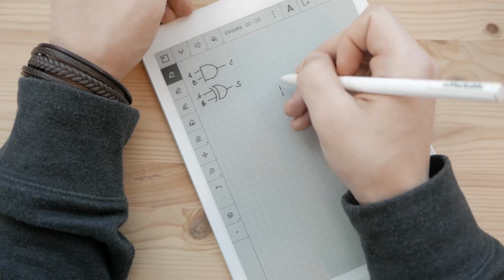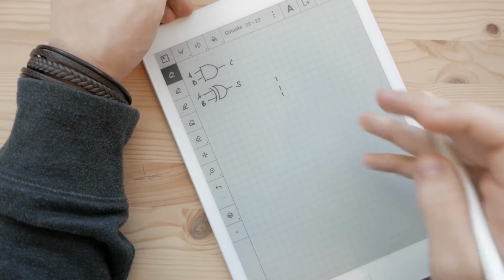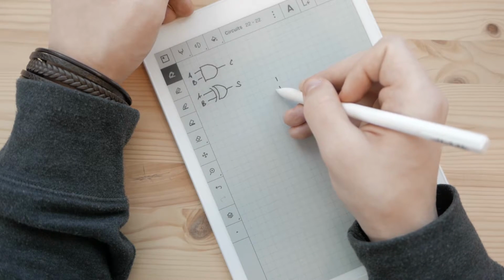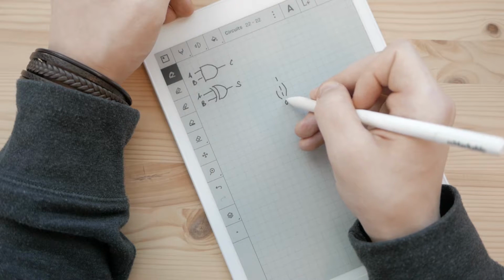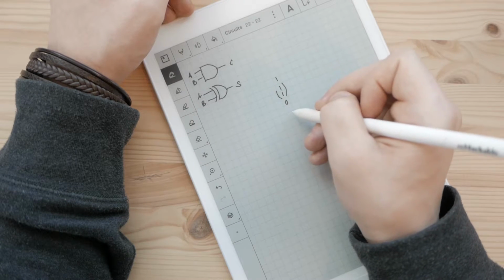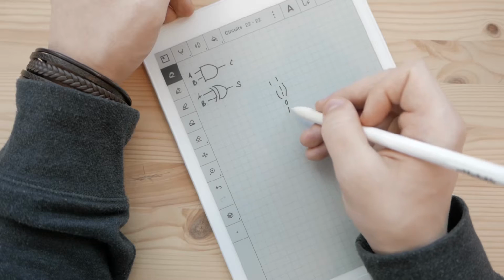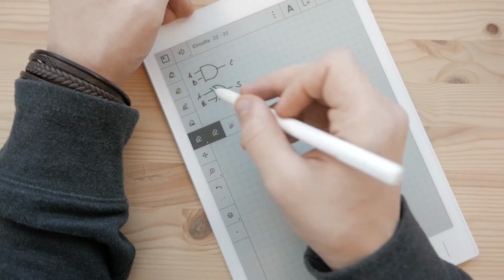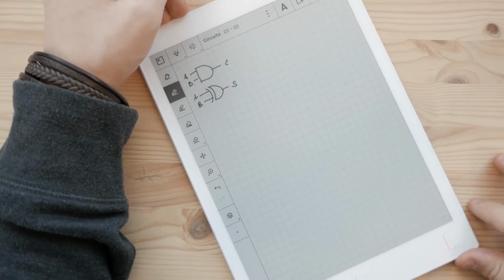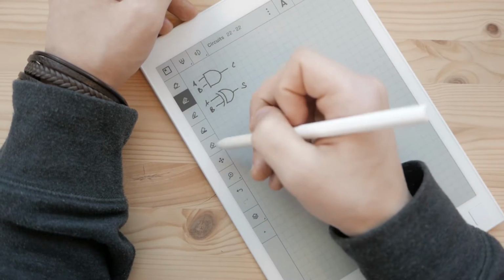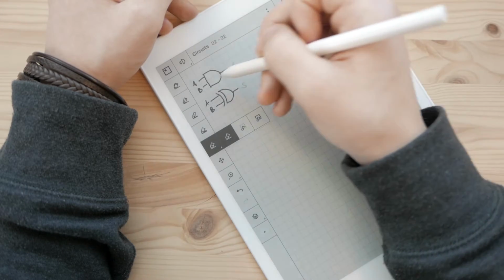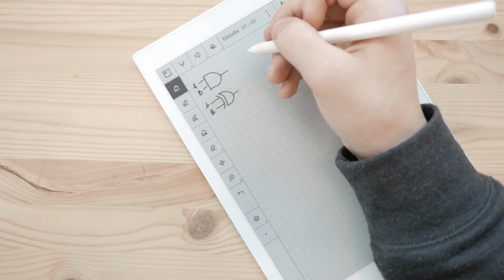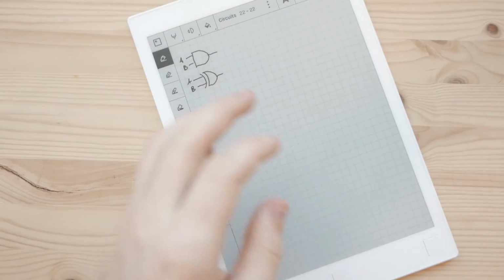And what if the numbers look like this? What if what you're adding looks like this? Well, then you'd first add these, that's a 0, but hey, I have another one I need to deal with, so that's a 1, and I still have a carry, so I carry out as well. So this is a half adder because it's a half. And how do you make a full adder? Well, how do you make a full? You add two halves. So let me just write that up.